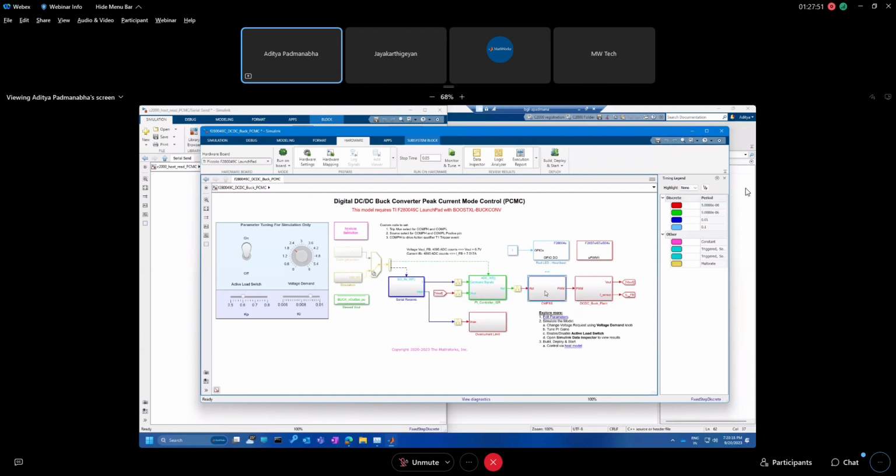Coming back to the code generation, most of it is triggered asynchronously through a hardware interrupt or serial interrupt. As we saw earlier, we configure PWM to run at 200K, and ePWM triggers the analog to digital converter, and the ADC triggers an end of conversion at the end of sampling.